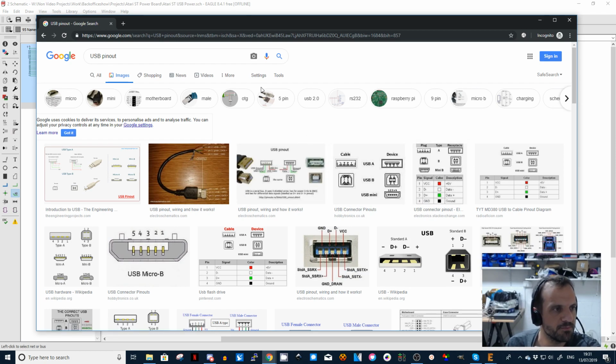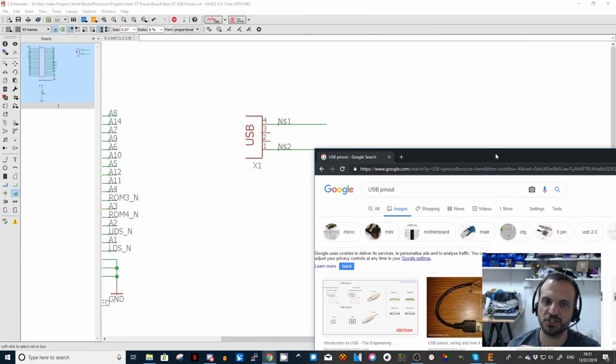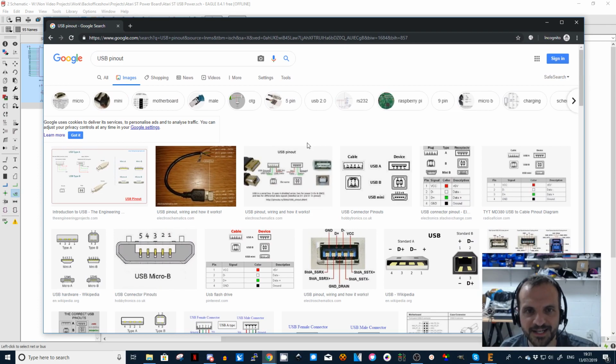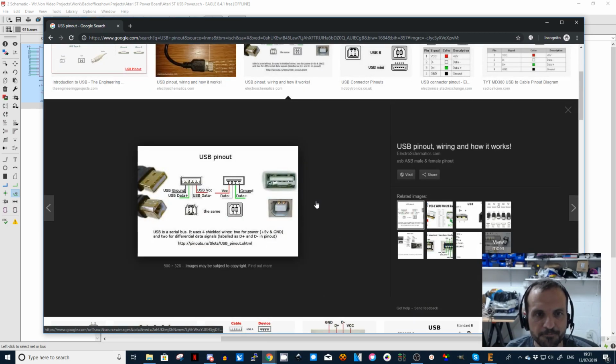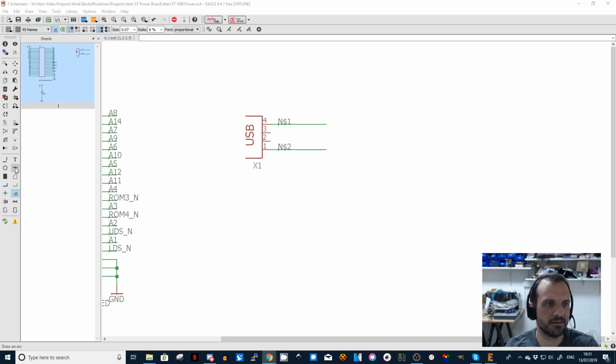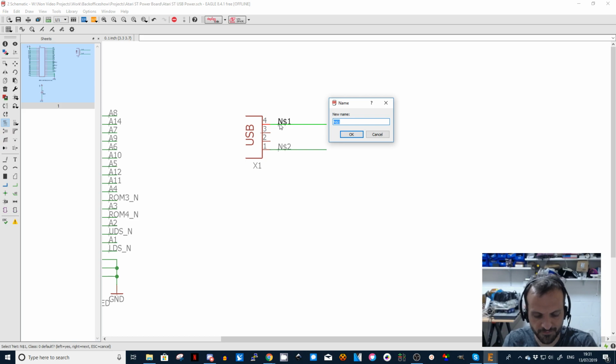Right, so USB is usually 5 volt. Yeah, for Ash, which is the 5 volts? Come on, we've had this issue with pins. I'm scared now. Is 4 the 5 volts or is 1? And this is here. So this is showing the socket end is suggesting that pin 1 is VCC and pin 4 is ground. So that extremely cursory glance is clearly enough. Ground.